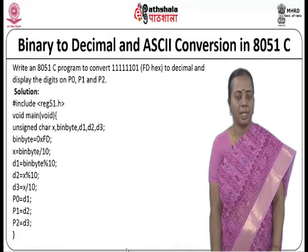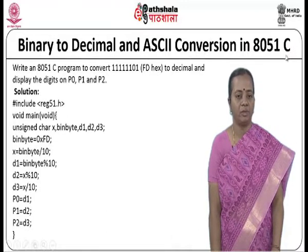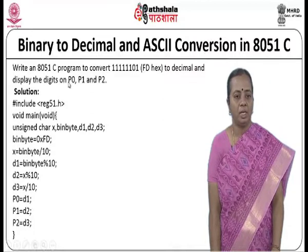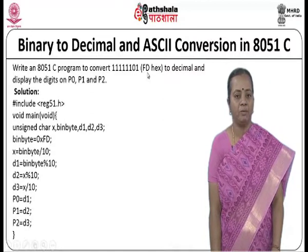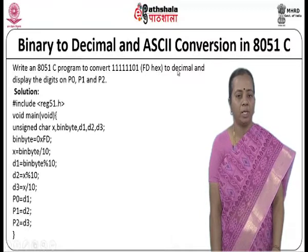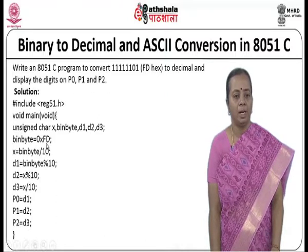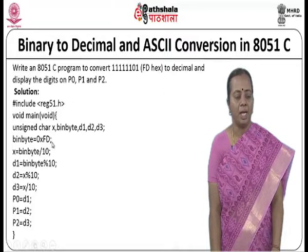So, this is another example where your data set is converted from binary to decimal and ASCII conversions in 8051C. Just see that if I am having something like FD as the hex data which has been converted into decimal and display the digits with your P1, P2, P3, or you will be having something like FD is the data, I need to find out what will be the decimal values.